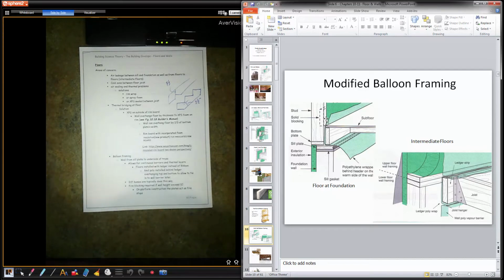In my opinion, sometimes less wood is better, again, for thermal, right? You're not compressing that insulation. But if you put a 3/4 inch piece of material there, that wouldn't really affect anything. It's if you try putting a 1.5 inch piece of material in there where you start to compress the insulation. So you can buy strapping that's 3/4 inch by 5.5. That would be perfect for that location. And then you just basically nail it in with a brad nailer or a stapler, almost could even hold it potentially.